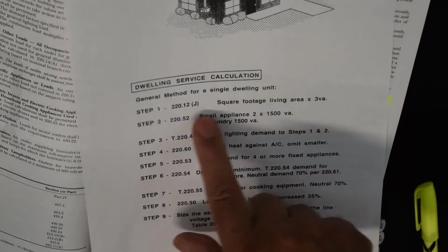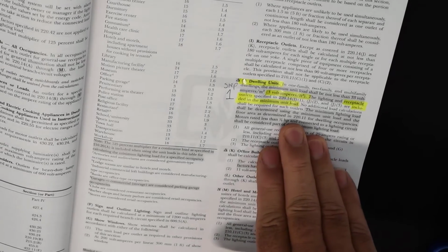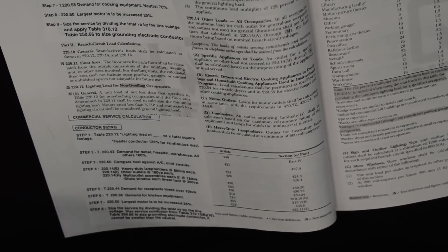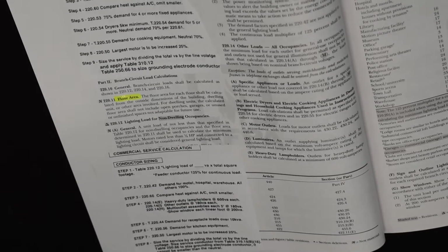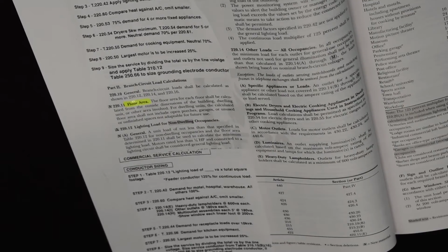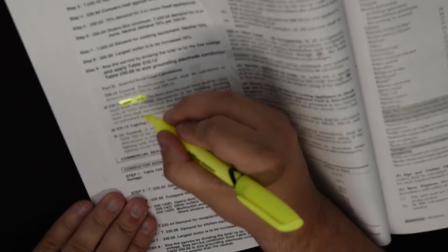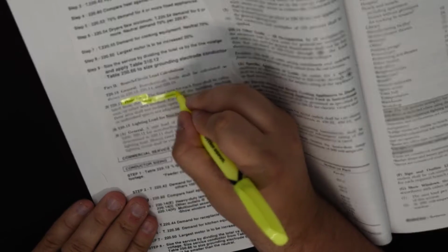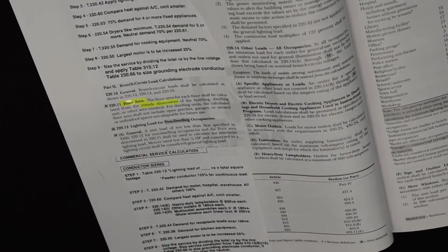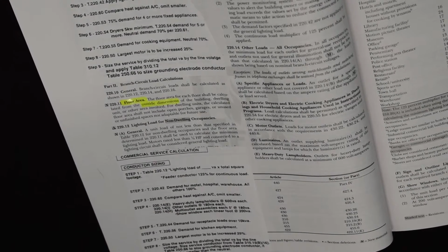Step 1, 3 VA. To go on with this J, we need to know about that floor area and how that's measured and what it includes and what it doesn't include. And it refers us to 220.11, which is over here. 220.11 says floor area, so let's highlight floor areas. It says a floor area for each floor shall be calculated from the outside dimensions. So highlight outside dimensions. We do not care how thick the wall is, which is a trick that some of the test providers for the state exams use. They'll tell you how thick a wall is. It doesn't matter. We're talking about the outside dimensions of the building or dwelling unit, or other area involved.